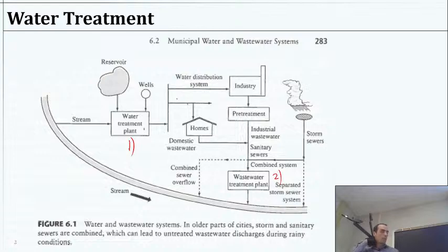Actually, there's a great example. You'll probably get a chance to hear directly from Caroline at Amigos. They have situations sometimes where they have septic systems that they're using, but during the rainy season, they just don't drain. The water table gets too high, and with clay, it fills up. And so what they've had to do is install valves to prevent their gray water from going into their septic system during the rainy season.